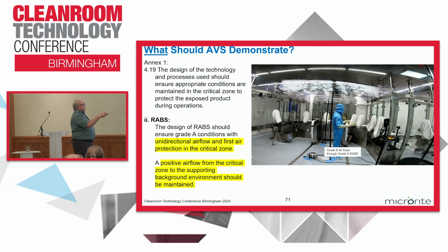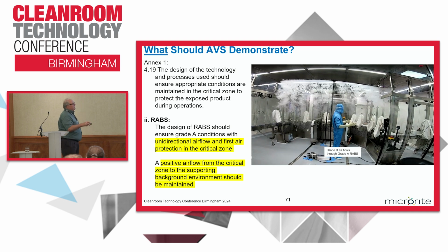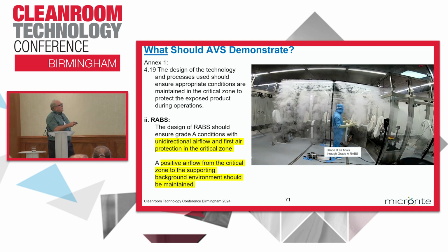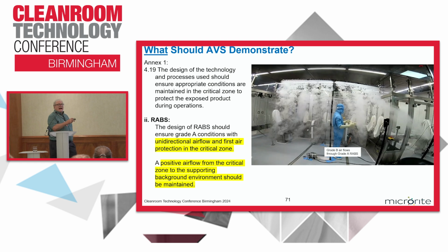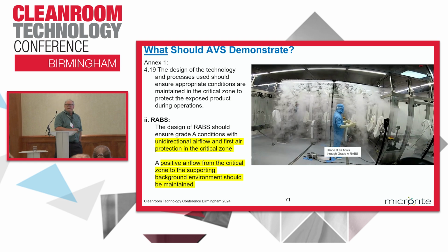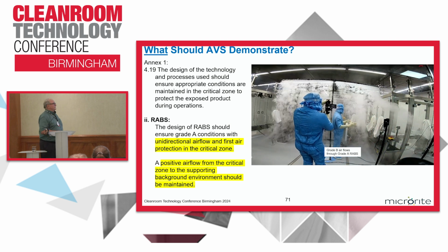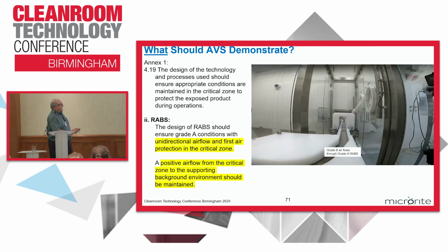Partially stoppered vials are filing into the lyophilizer via this conveyor, yet it's really clear, and you'll see that air is flowing from the grade B occupied zone through the conveyor, through the grade A zone. And this was a brand new installation. They had no idea what was going on.